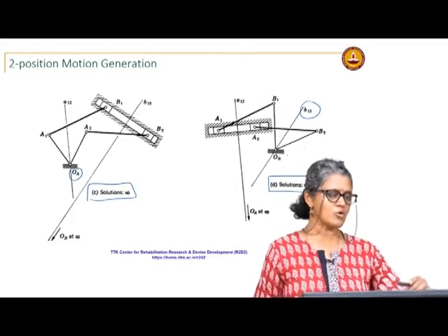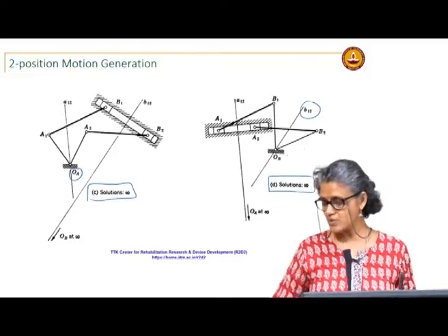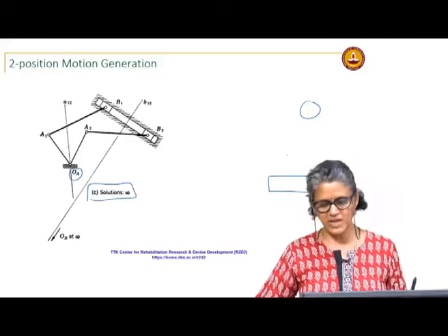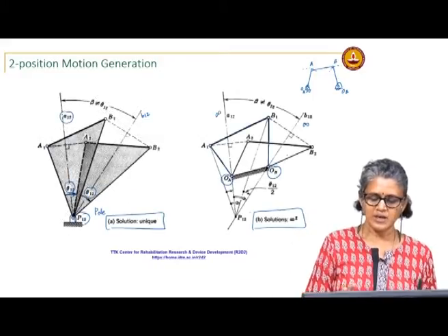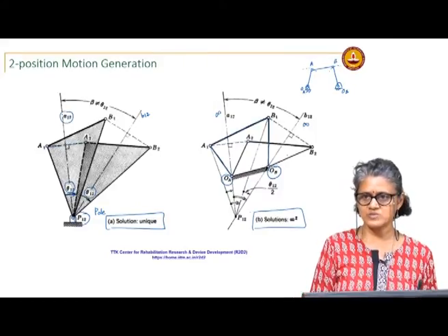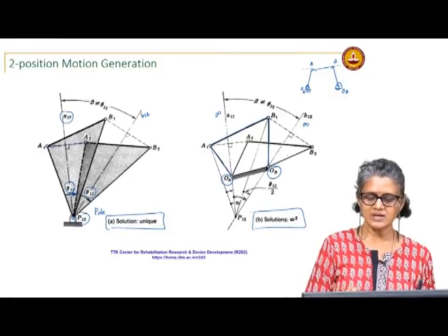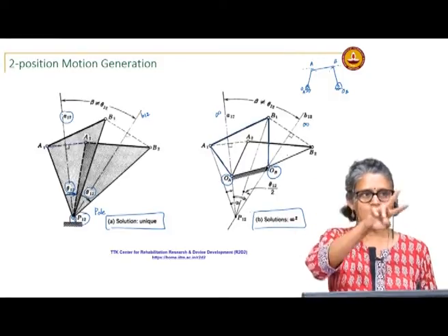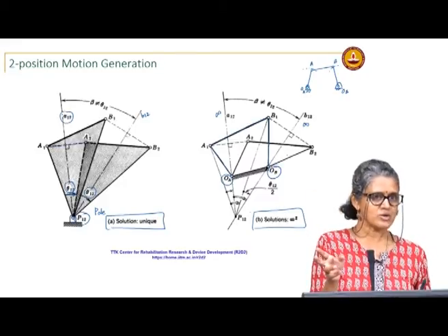So, it may go past on this side or this side; you are not really looking at how the linkage behaves beyond here also. I am saying it will achieve A1 B1 to A2 B2 if I use this 4 bar, but there is nothing to say that it will only move between these 2 points. These two are not limiting positions that I am looking at.